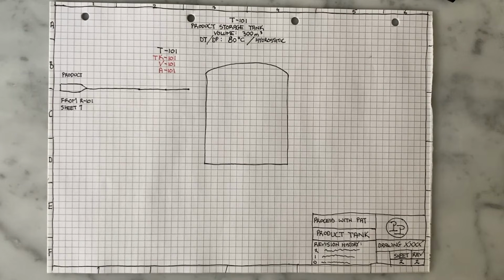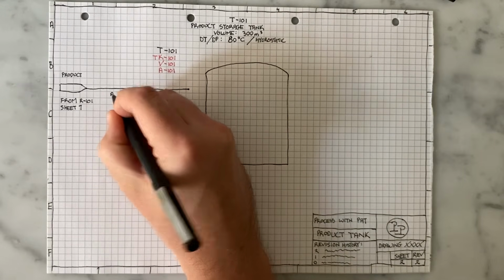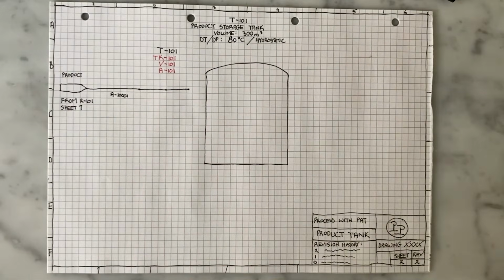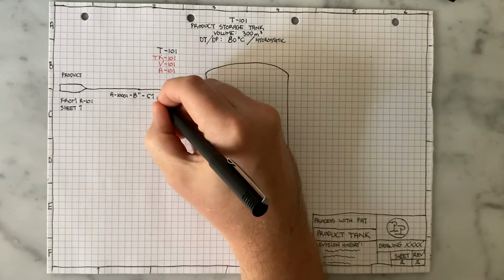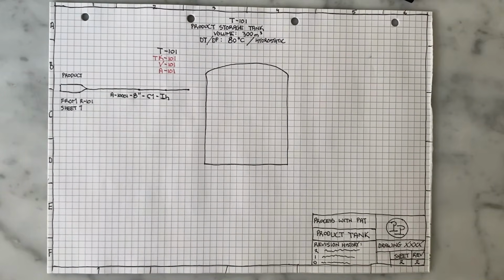Now that we have a line running into our tank, that line needs a number. The label that we put on the P&ID is going to contain a lot of information. The order of these different pieces of information will be specific once again to the site. So what I'm showing you here, I've completely made up. The first letter is what we call a pipe fluid code.